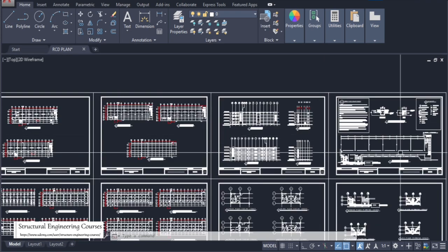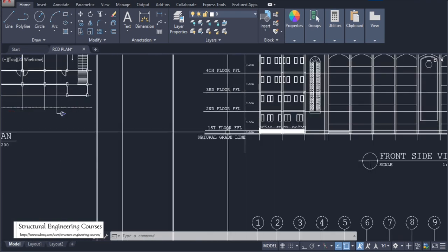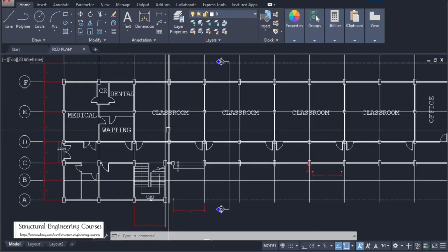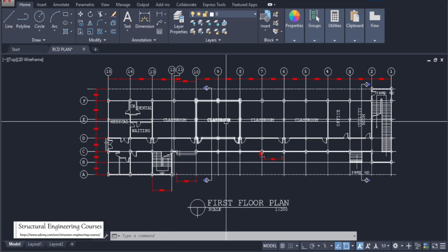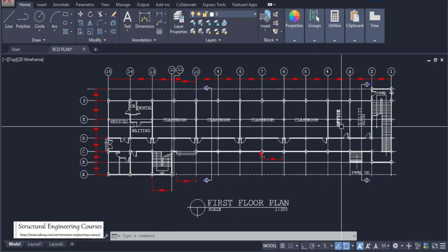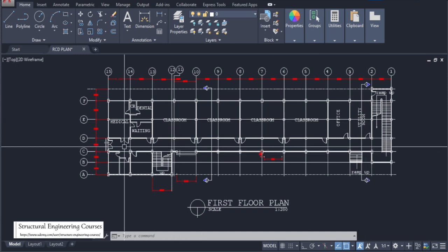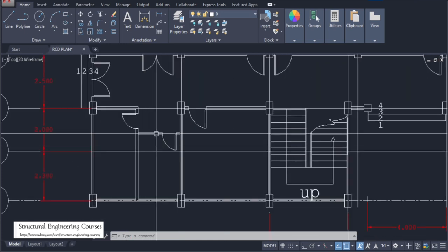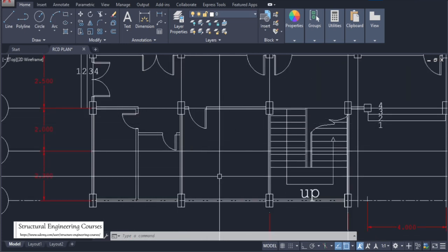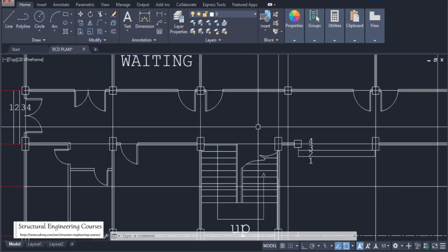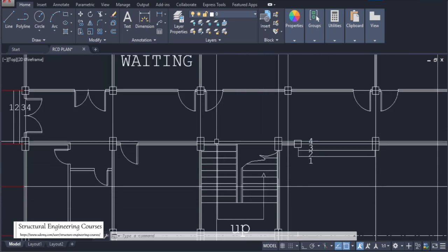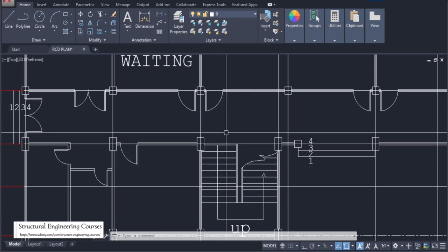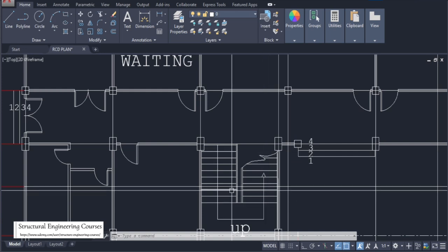Coming back to the plans, if we want to see the first floor finished floor level, which is at 0.6 meters, here we can see the simple first floor plan. We have 1, 2, 3 and 4 classrooms, 1 office, utility room, and one big corridor here, and corridor width is approximately 2.5 meters. This is a washroom, and this is a storeroom. This is a staircase for access to the upper floors. The flight is starting from here. That is why this is marked as hidden, because if we are standing here, we won't see the full flight from this point to this point.